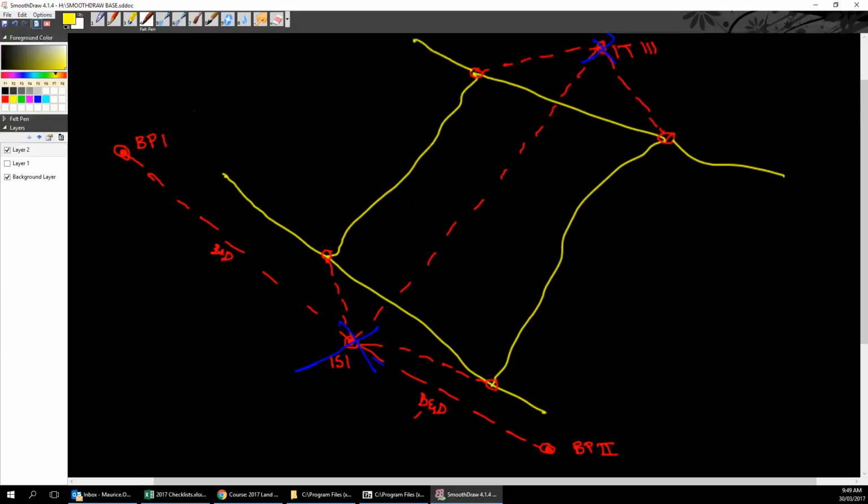So we might find that these marks here, that one there and that one, are both there, and perhaps we usually need 3 old marks before we start a survey. So let's just say that there's another old mark down here. So we'll just go into red, put that in there. So we'll go into red down here, and that could be AP3 from another survey down there.